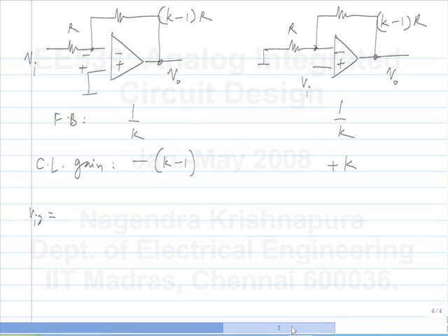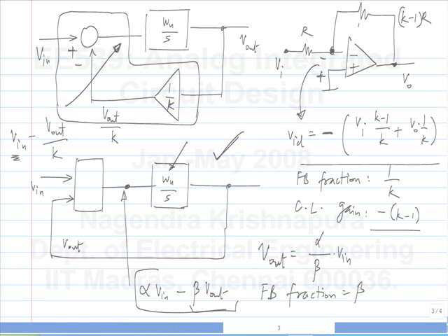So what I wrote here is the transfer function of the feedback network. Okay, this is the function of this one without the feed forward block. If I have a certain V out here, what voltage do I get at this point? That's what I wrote. And if you place the op-amp there, it will get forced to 0. Right? So this network N will provide me alpha Vn minus beta V out. And it will get forced to 0 if I place N in feedback around an op-amp. Okay. So that's how I get alpha by beta.